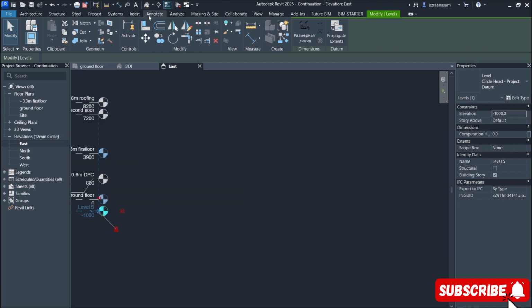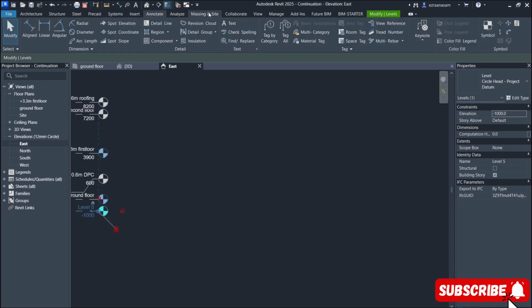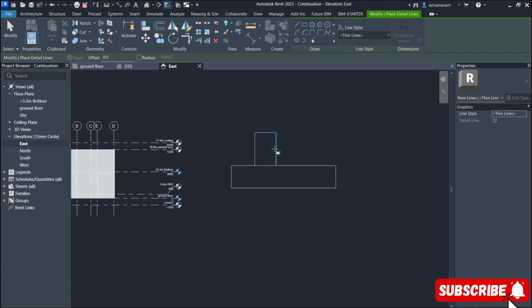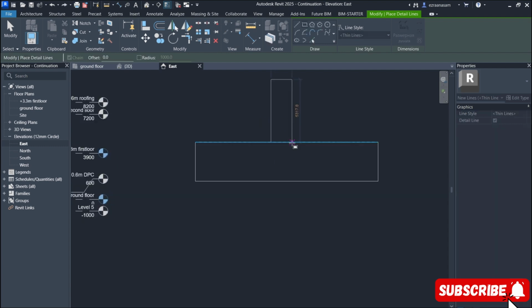But I want to explain what a slab foundation is and also what pad foundation and pile foundation are, which I believe, like I said, you have knowledge of from civil engineering, but let me just brush over it quickly. Pad foundation is when you have something like this and you have a column here. So this is a foundation. What is pad foundation? Pad foundation is a foundation where a short foundation like a slab is placed under the load bearing element.